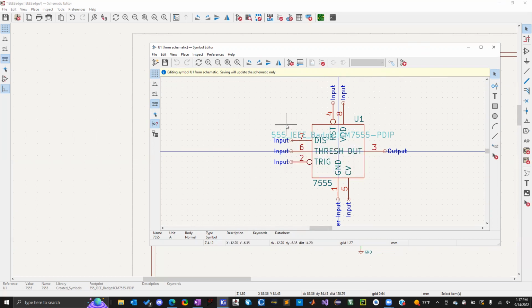Another change that I have to do all the time is usually changing what pins are inputs or outputs. As you collect more symbols from the internet, sometimes it transfers in a weird way, or whoever made the design was lazy or maybe didn't know as much about KiCad pin inputs and outputs. For the most part, it's not important. They are just for the software to give you warnings like, hey, you have an output to an output. That doesn't make any sense. It should be input, output.